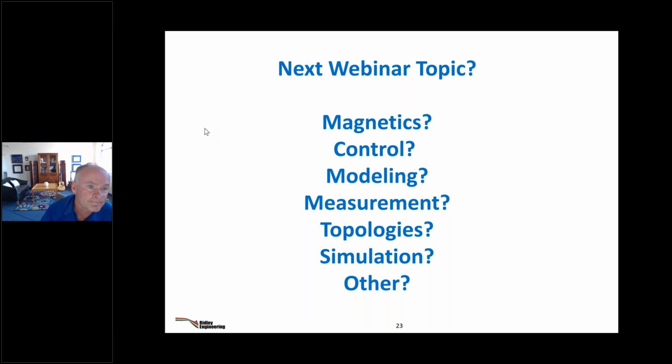Capacitor charging. That's tough because if you're capacitor charging, you've got a big range operation again. You're starting at low voltage and you've got to charge up to full voltage. So you're designing an LLC that's got to go over a big range. There's lots of other ways of doing zero voltage switching. It's not just the LLC that has that. So look into those too.